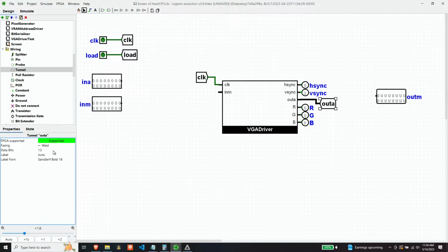However, the CPU also needs to be able to access video memory, because it may be necessary to read the 16-bit value out and twiddle a few bits and then write the value back in. So you may see the dilemma: what happens if the CPU and the VGA driver simultaneously need to either read from or, in the CPU's case, write to RAM?